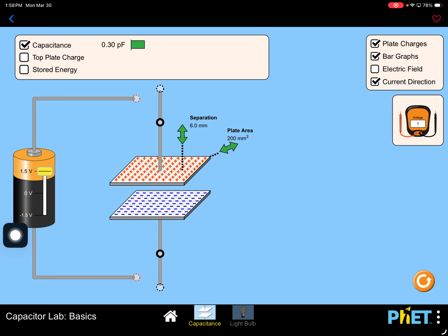All right, so we want to see how the capacitor discharges. Again, this is a closed loop, and so using Kirchhoff's voltage rule, we can set up an equation. So let's go across like this. That's what this circuit is. When you go from here to there, you're going from high to low voltage, so it's minus Q/C. And then you're going against the current, so it's plus IR equal to 0.